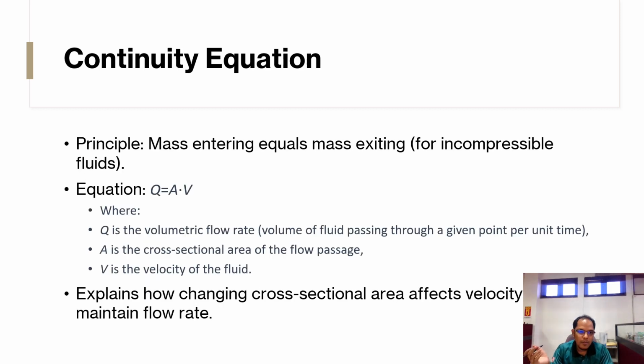Okay. So this is the continuity equation, where in principle mass entering equals mass exiting for an incompressible fluid. The formula is Q equals AV. A is the area, and V is the velocity.